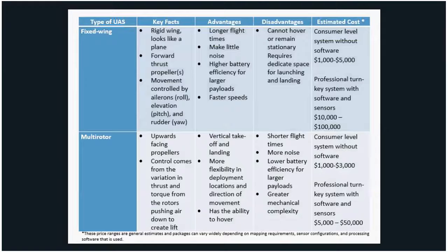And I haven't really looked at measuring vegetation that low, but just trying to measure the ground surface with survey grade GPS, we were getting accuracies down into the 10 to 20 centimeter range, and so you probably could, but I don't know for sure how the grass would show up, as we were measuring the top surface versus the area around it.